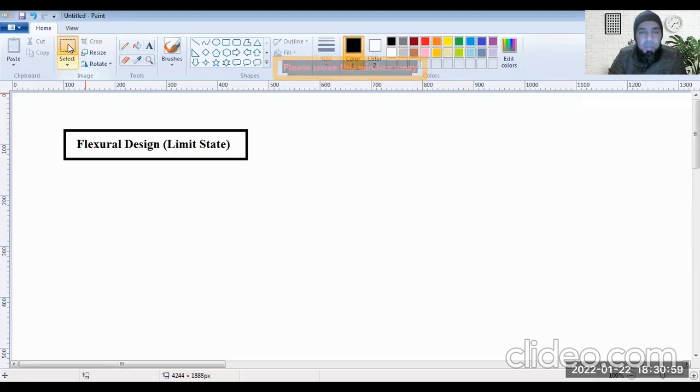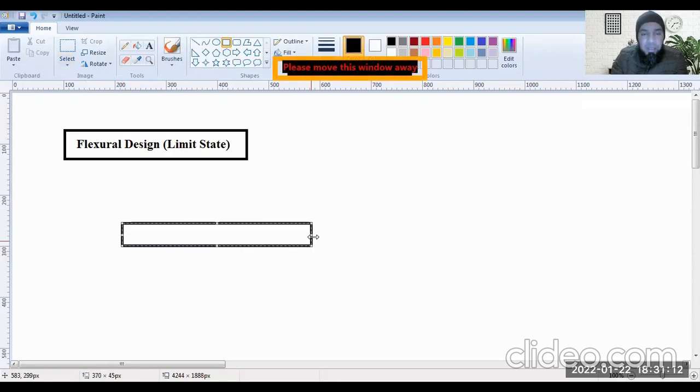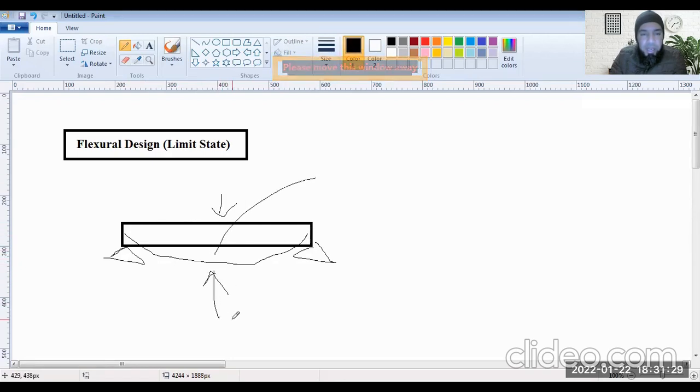For example, you might get the flexural stresses for concrete, but it still is not pure compression, neither is it pure tension. It's a combination of both the two states. For example, if you have a beam, flexure means it's under bending. Under flexure, this beam would undergo tension towards the bottom side and compression towards the top side. So it's not under pure compression, neither under pure tension.